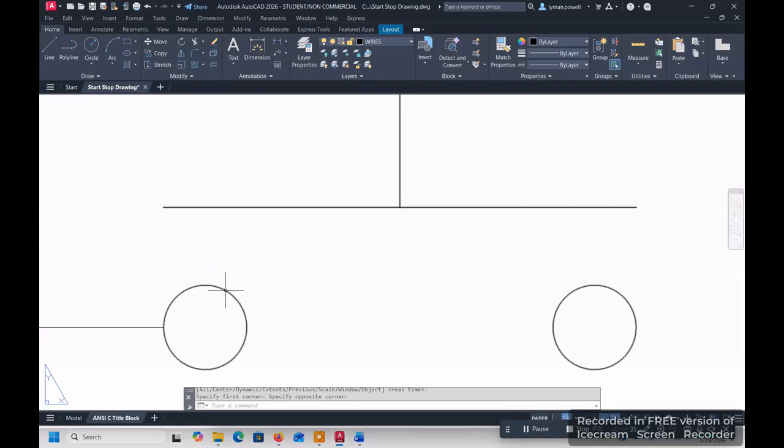So we're going to just select this block, and first we have to explode it, and that will make it so we have individual pieces. And for some reason it didn't explode. So that it is exploded, so we have each individual piece that we can work with.